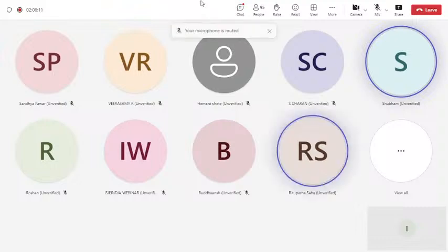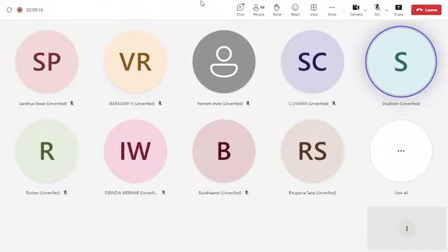No, it will not affect much, because this support is basically used if you have an overhung object. You are using an additional support, so it will not affect much, because after that you will remove it, and you are using the same material only. If you are using a different material, it will affect, but it will not affect more, because only one or two layers will be connecting with the support that you are giving.